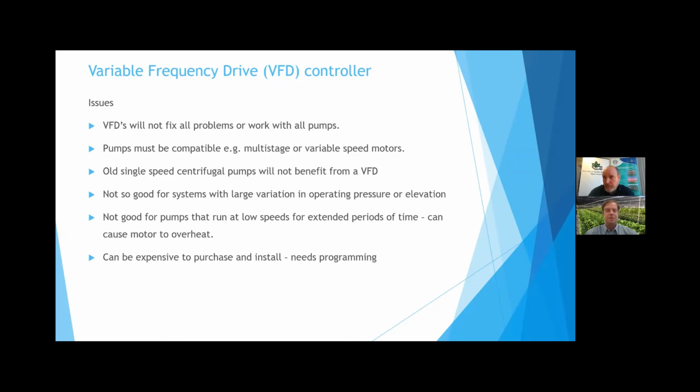And just on that topic, you need to really assess before you put the VFD in or put a pump with a VFD on whether you're going to get a reasonable payback. And that comes back at least partly to how much you're using the pump. If you've got a situation where, yes, you have big variations in your flow, and that indicates that the VFD would be a good thing to put in, but you're only using the pump for an hour a day, it may take you 25 years to get your money back on energy savings with putting that system in. So you've got to keep those sorts of things in mind.